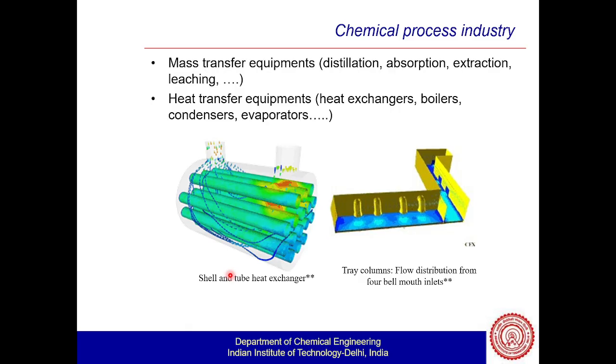So, going to the chemical process industry, you have fairly seen in your BTech this is what we call the shell and tube exchanger, where certain fluid flows in the shell and another fluid comes in the tube, and they exchange heat between the two. We basically used the LMTD approach to find the heat transfer between the two fluids, but that's not the case when there is a non-uniform flow inside the system. Then we have to solve the heat transfer along with the momentum and continuity equations to get the whole velocity and temperature profile inside the system.